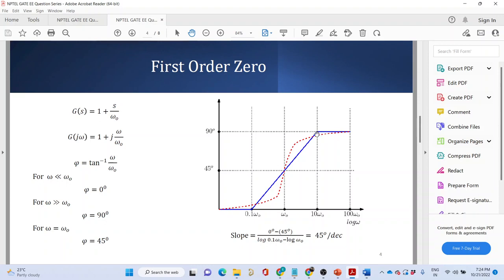Since it is an exam and you are given all these mathematical models, it's different from when you are conducting some experiment or doing some research, where this kind of asymptotic Bode plot would not be there with you. You have a system, you find its frequency response, you change the frequency, you see what its magnitude and phase is, and based on the information from your frequency response experiment, you have to find out where the poles and zeros lie.